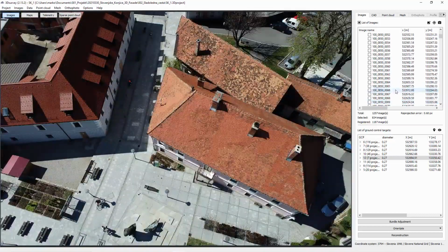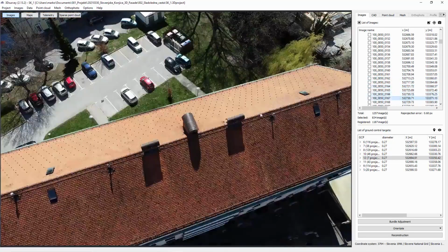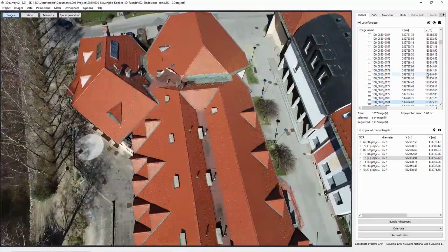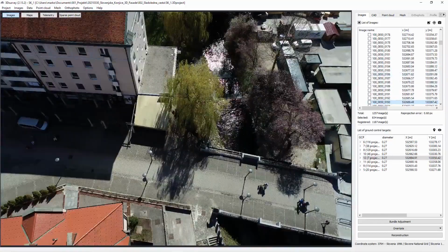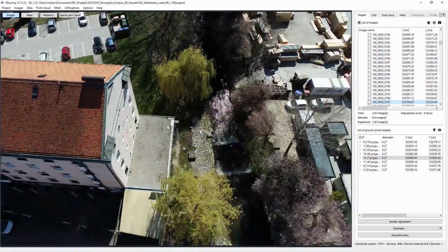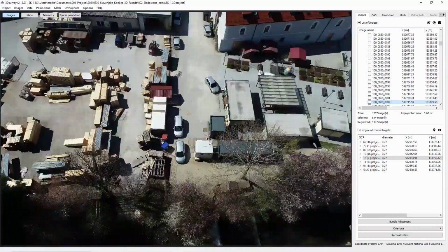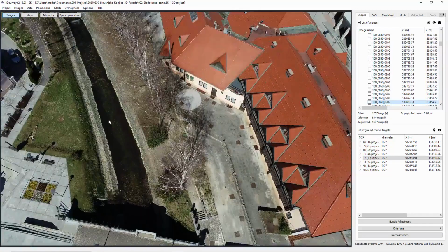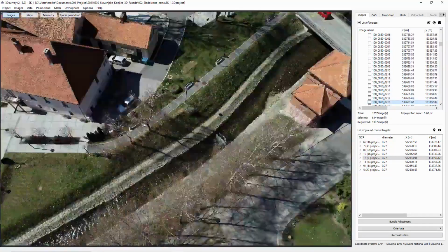I think we have approximately 200 images with the manual mode, plus the automatic mode with the double grid missions. Here we are still in double grid. Even if I select just my city center road, the drone goes and captures a wider area, so we definitely capture too big an area, but nevertheless it's better to have more data than less.